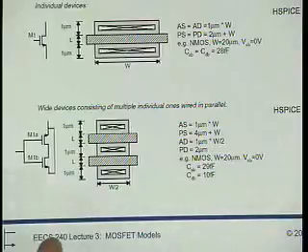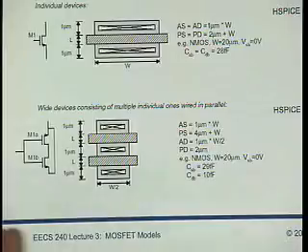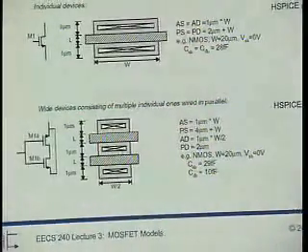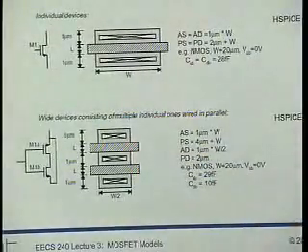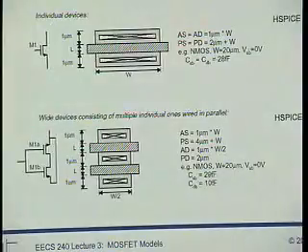With CGS, the story is a little bit different. If you figure out a way to get rid of CGS, you probably have gotten rid of the transistor, right? It's really intrinsic to the operation of a MOSFET that you have a gate capacitance. So the intrinsic CGS we really can't do a whole lot about, unless we don't want the transistor in the first place. But the extrinsic capacitances, there we can do something about.